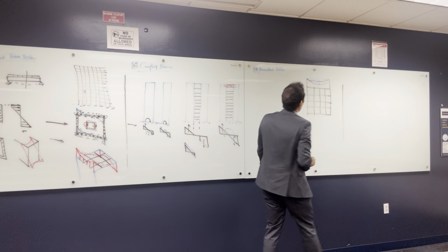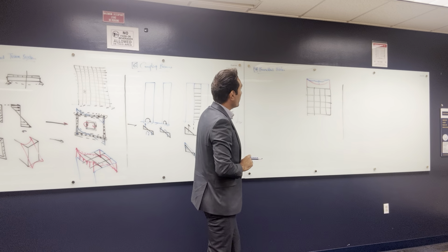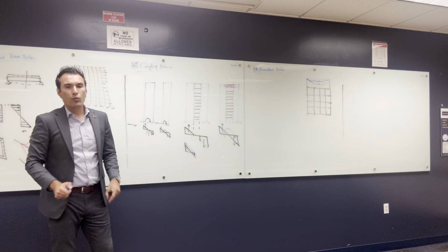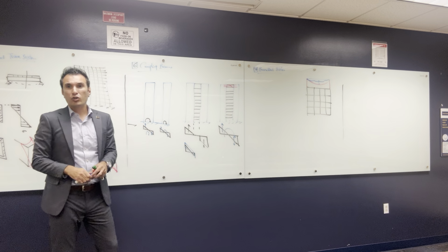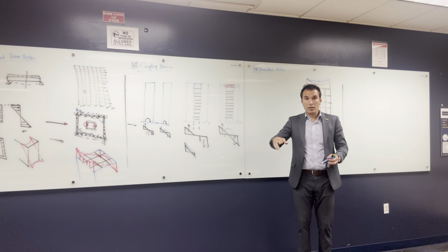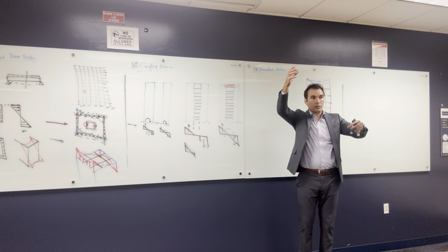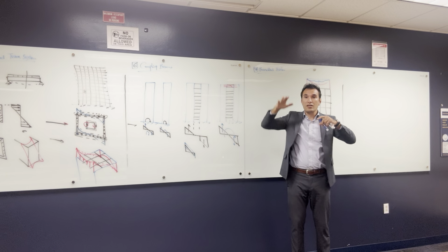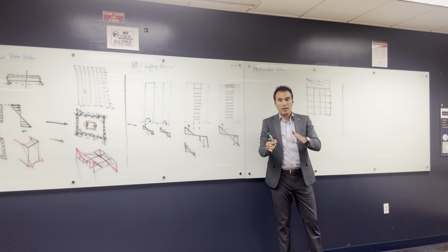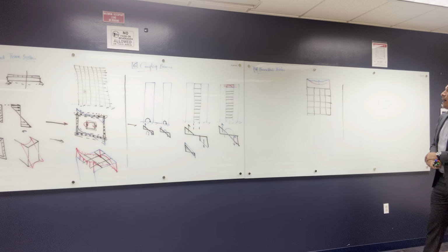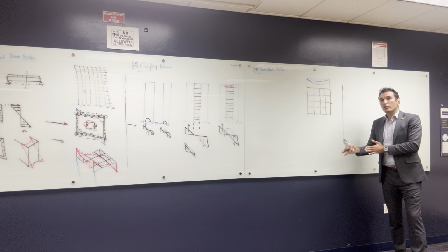All right, so that's what we call the bundled tube system. And actually there's a building that maybe you guys know in Chicago, the Willis Tower. It's built with this bundled tube system. How? They make the bundle of 9 tubes, and they make the tubes stop at different heights. So not all the tubes go until the top height. So they want to make it in a good shape. I'm gonna show it in the presentation a little bit, but I just wanted to show you how the shear lag looks like. Okay, so it's better to decrease the shear lag.